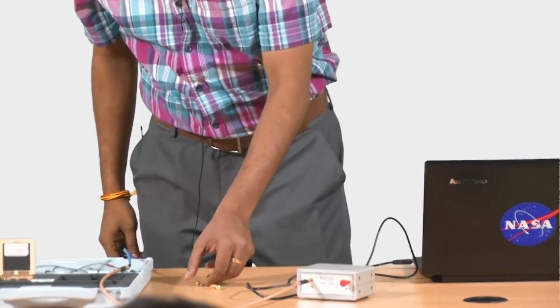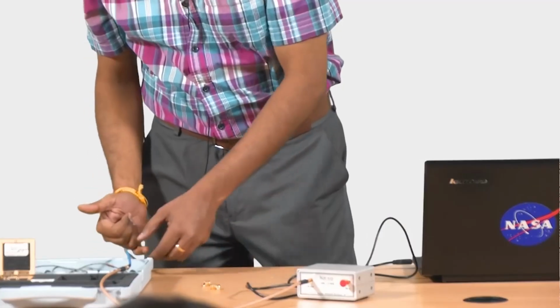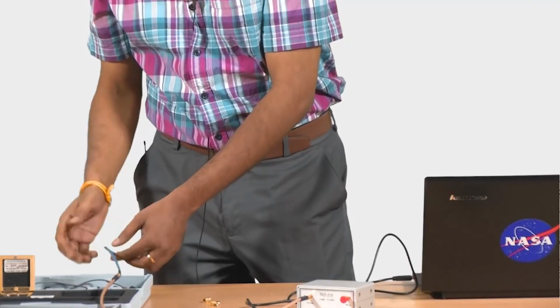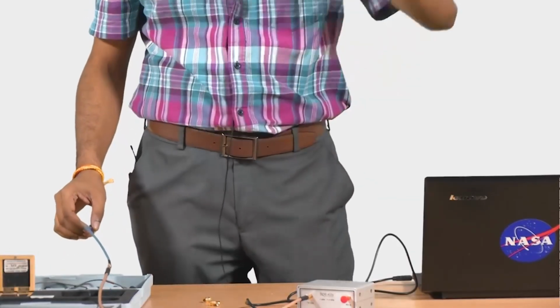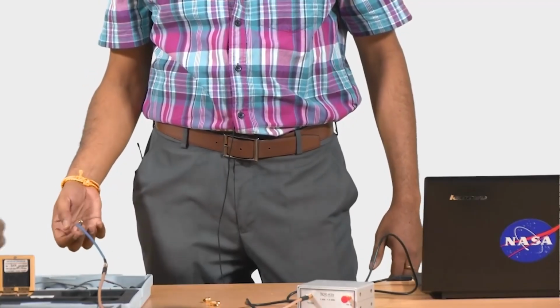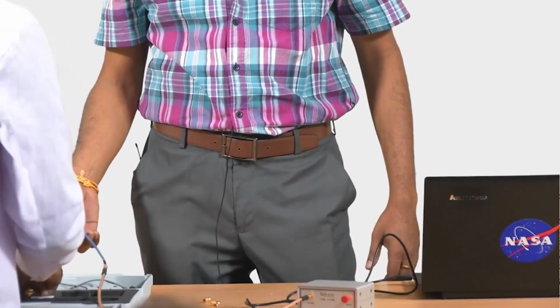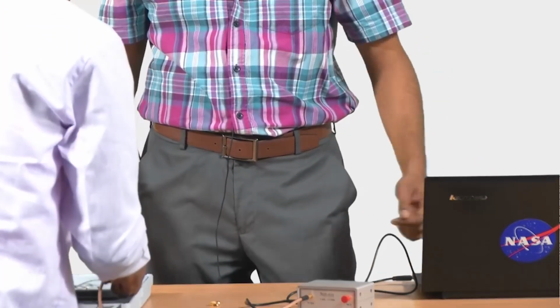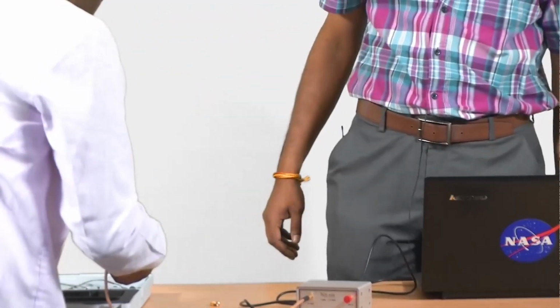We could also say that the load can be open, now we can short it. You can short it, but shorting will again move in the constant VSWR circle. Yes. But we can connect a load. Shall I put the load itself, 50 ohm? Yeah, because it will be impedance matched. It should come to the center, right?